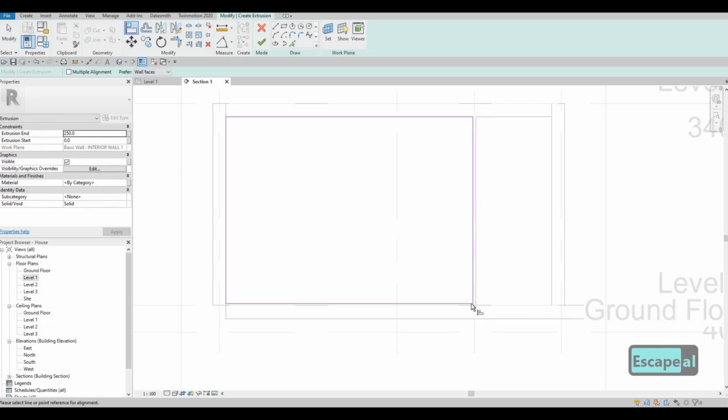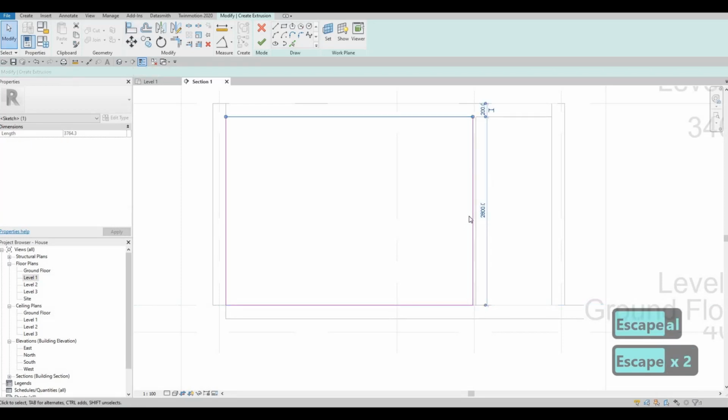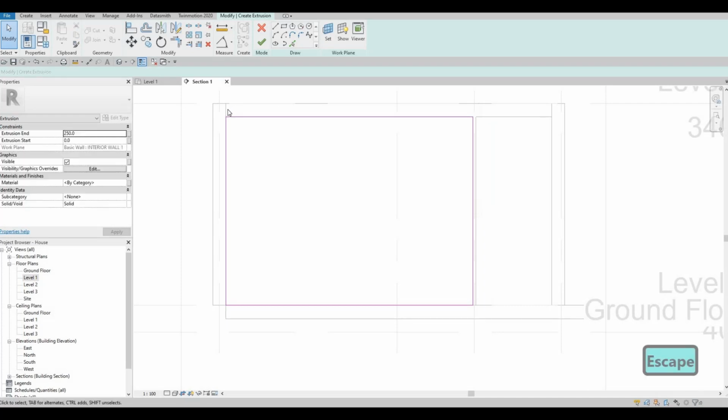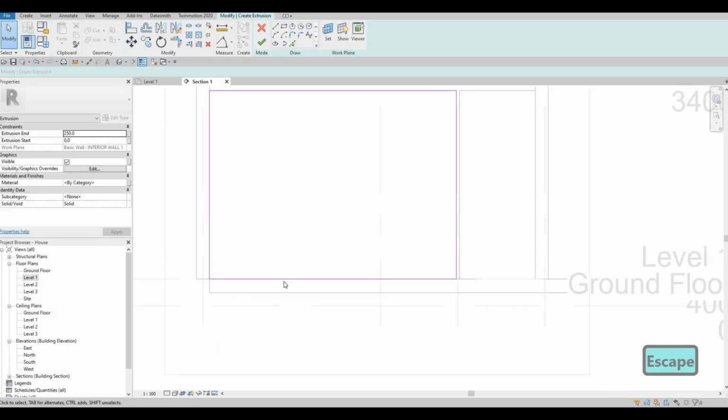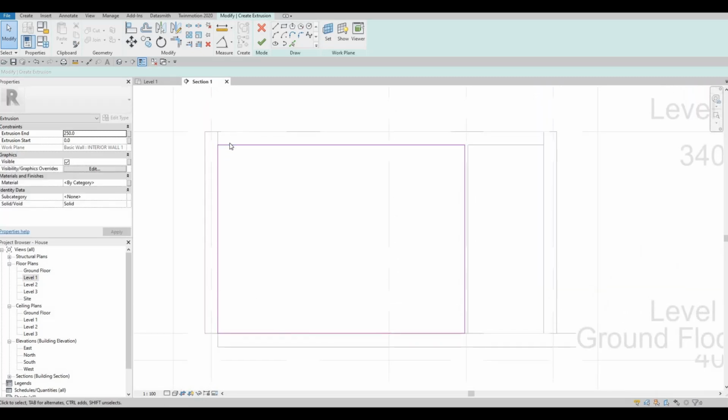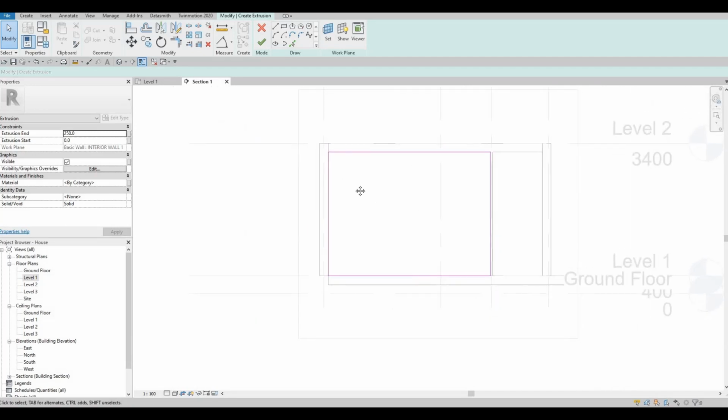So we're going to align it from the floor, and if you check, this is exactly 2800, and we created some gap here so that we could add the flooring later on, similar to the ground floor that we have right here. It usually goes down for the floor.